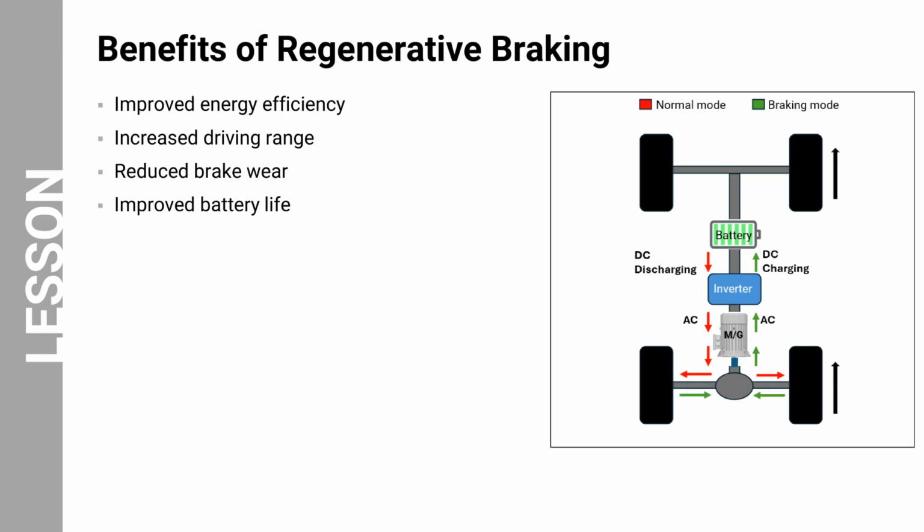Additionally, regenerative braking minimizes the use of conventional friction brakes, reducing wear and extending their lifespan, which leads to lower maintenance costs. Finally, the recovered energy is stored in the battery, reducing the depth of discharge and helping to maintain the battery's health and long life.